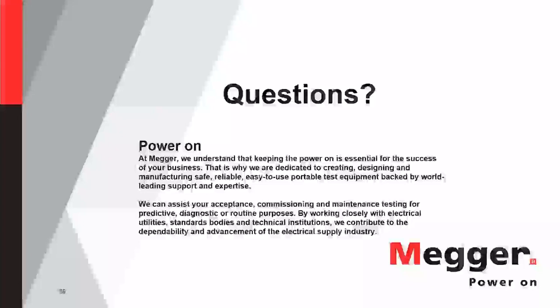What I have seen is sometimes with your analog transducers, you have this resistor. It's a mechanical device, so it's sliding back and forth, and eventually it wears out some. As far as calibration goes, generally what I do is I look at the motion and I see, hey, everything's looking fine. We're getting the proper stroke, what we're expecting. So I'm not that worried about calibrating.